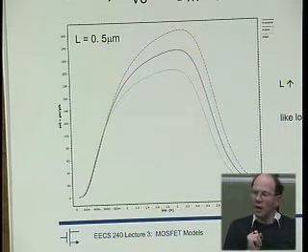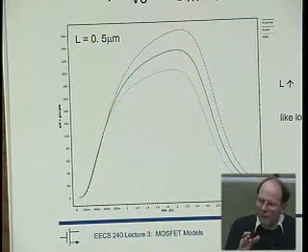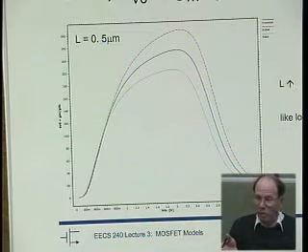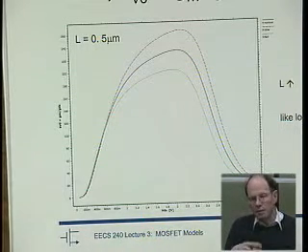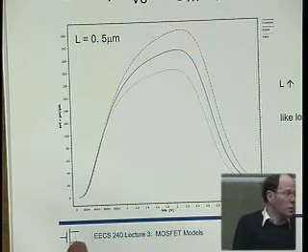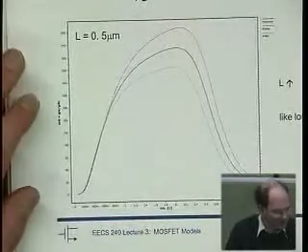So if you need gain, then you usually want to use a little bit longer than the minimum channel length. Using much longer would still help, not quite as much anymore, but then of course we have this fT business, right? And so very often we don't want to use really long channel lengths because they are dogs otherwise, right?